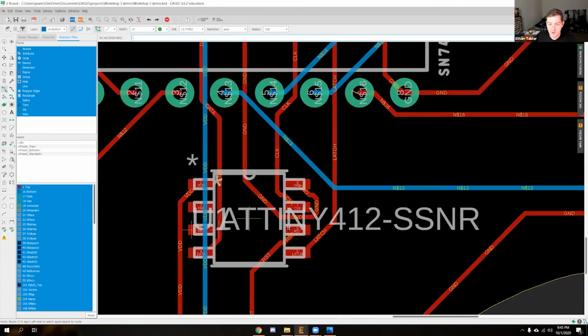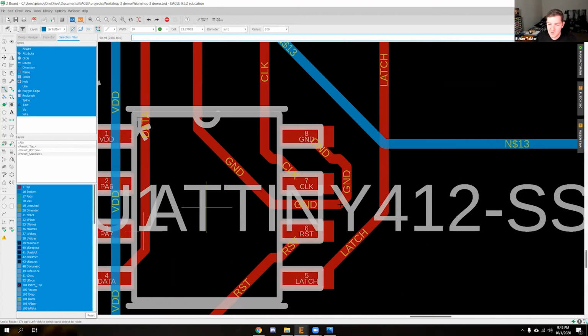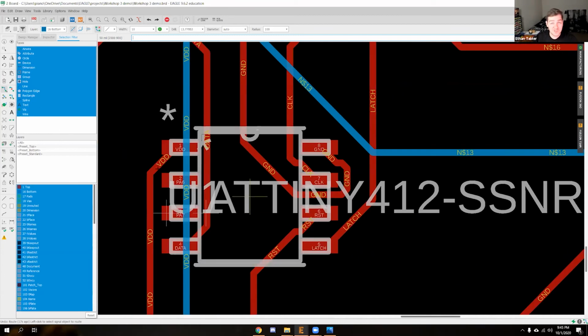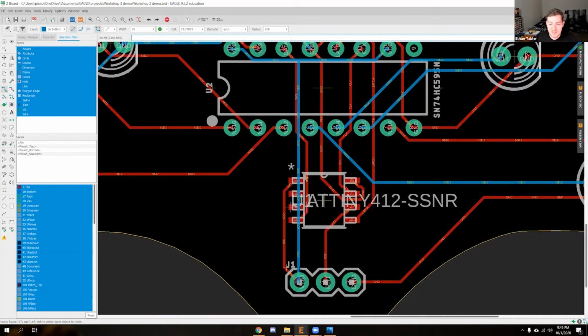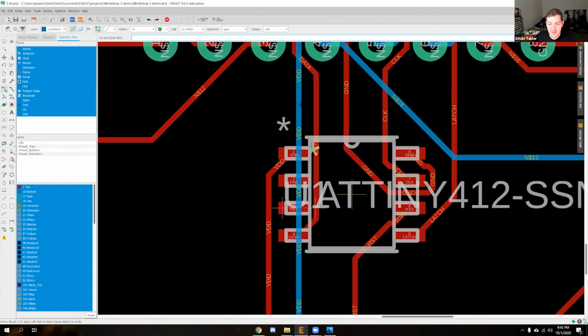You'll see down here, though, that it's pretty darn close to these signals and stuff. Because this is a surface mount part, which means it does not go through all the way, it can only access the top layer to do its signals. It can still go to vias, and it can still link to other traces. And you'll see that actually this bottom layer, this VDD on the bottom, completely intersects to those, but because it's on the opposite side, you can do that.